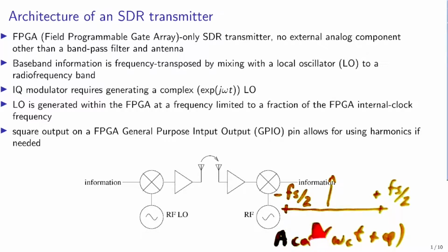So naturally, with software-defined radio, if we wish to create an asymmetric spectrum, with a positive part that is not the symmetric of the negative part, we will have to replace this real quantity with a complex number. By doing this, we create both quantities in phase and quadrature.